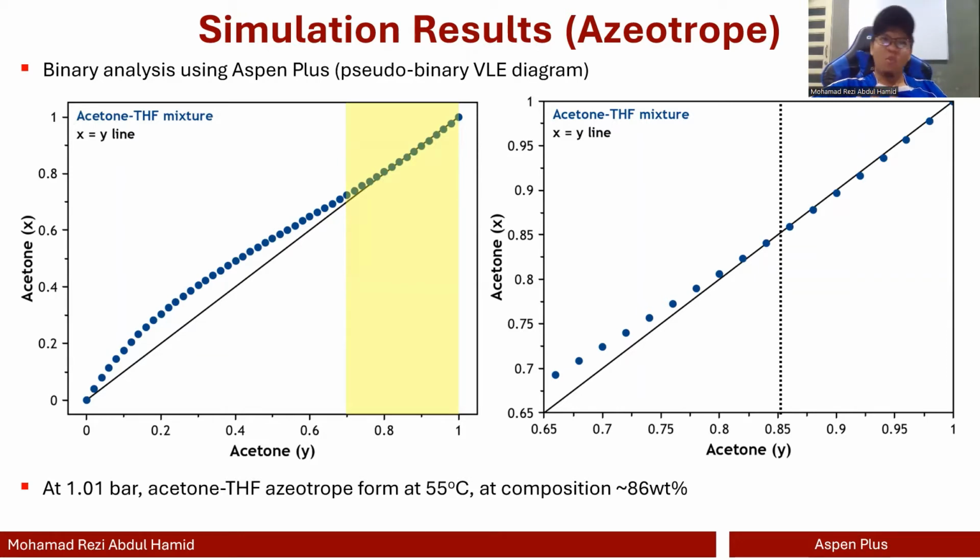Normally, the common one that you always see is called a TXY diagram, where you have the temperature in the y-axis, and here you have the composition of your component, in this case acetone, in mass composition or mole composition, and then you will have two plots, one belonging to the vapor phase, the other belonging to the liquid phase.